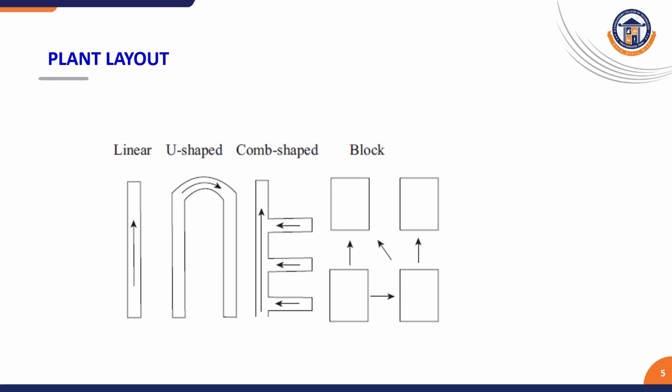When I say small lots, let me take an example of a t-shirt. I have only a 5,000 pieces order for a particular design. Please understand, today lots of t-shirt designs are coming out. So if a buyer orders 1 lakh pieces, he gives 20 different designs. The colors may vary, no problem, but the basic design. So 5,000 t-shirts per design. This block layout is suitable, wherein 8, 8 and 8 sewing operators, a total of 32 operators, will be situated in different areas. But one disadvantage here is you need a lot of space in the industry for this particular block layout.